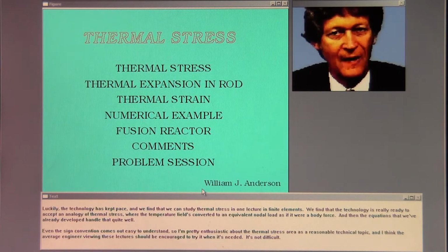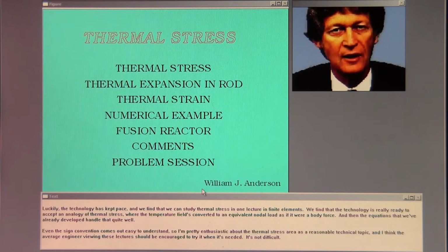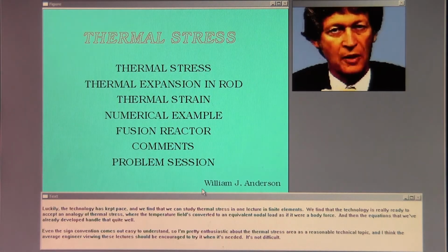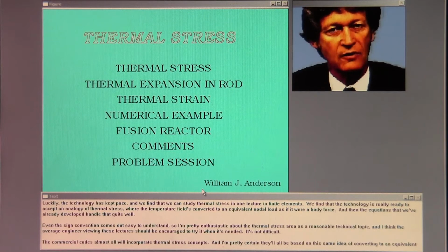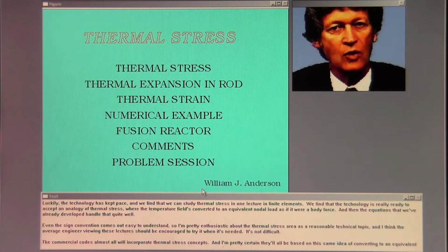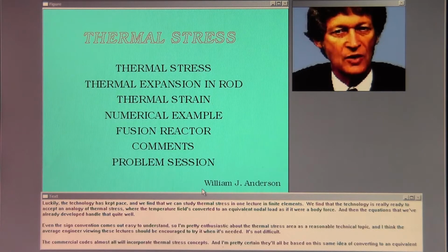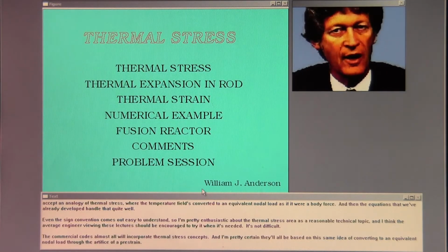elements. We find that the technology is really ready to accept an analogy of thermal stress where the temperature field's converted to an equivalent nodal load as if it were a body force. And then the equations that we've already developed handle that quite well. Even the sign convention comes out easy to understand.